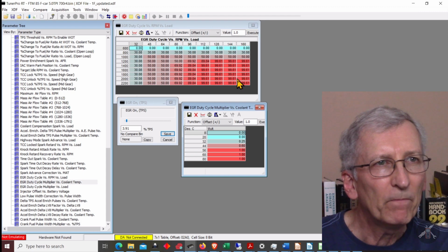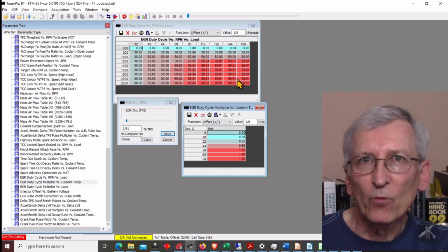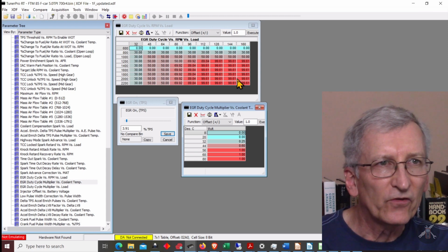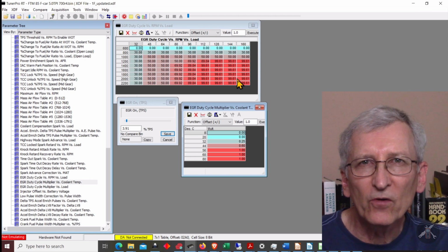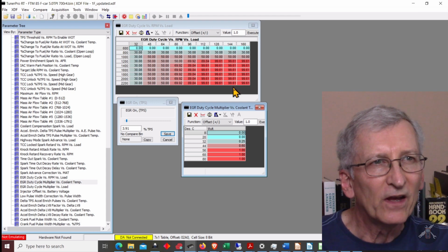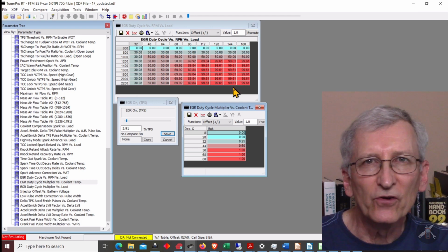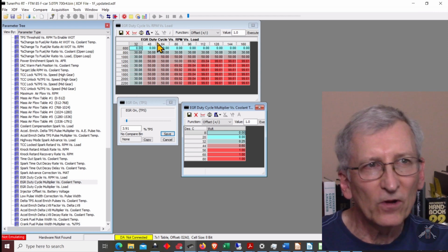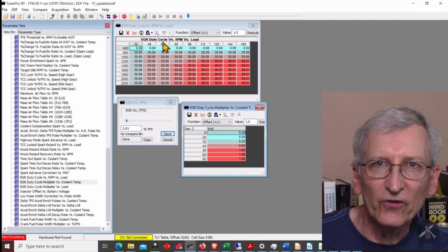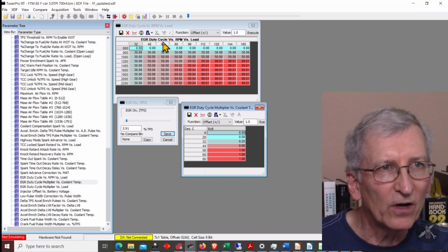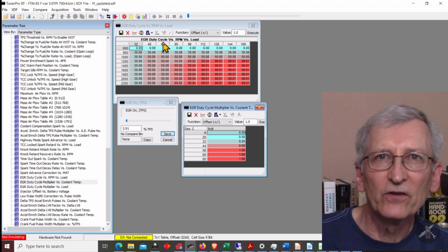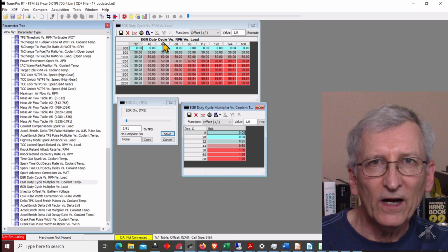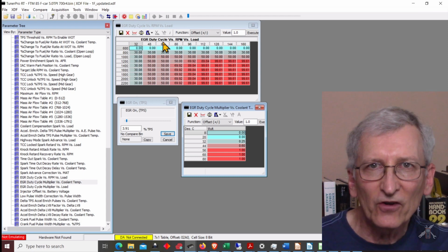But I think, from what I see, it's an issue of where you consider plus and minus. And even though it says EGR duty cycle, it's not EGR solenoid duty cycle, it's more like EGR valve duty cycle. It's like as power comes up, I'm trying to drive the valve more and more open. Now, one more oddity in these EGR systems is,